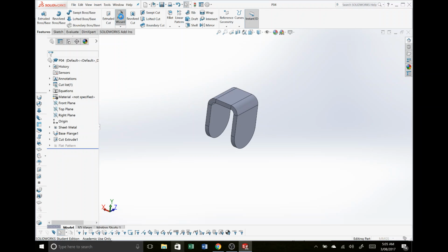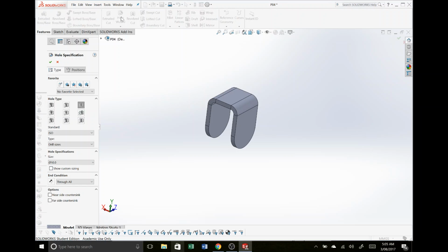It'll take a little bit to load because it's a fairly involved feature. And you can see I've got all kinds of settings. I'll get you to have a play around with those in your own time and just figure out what they all do. They're pretty excellent and super useful, especially things like the counterbore hole where you just want to hide the head of a screw, or things like the straight tap where you want to specify a threaded hole or something like that to an engineer that might be creating the part for you.